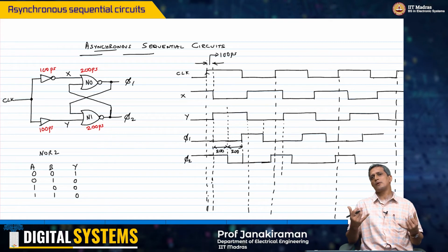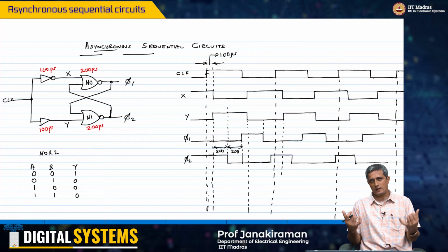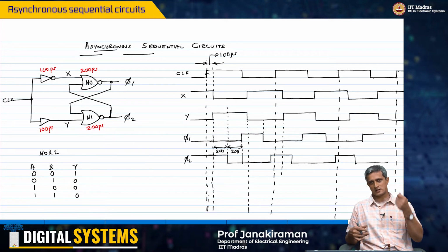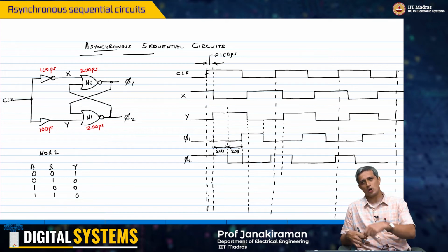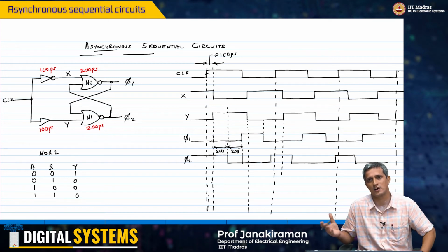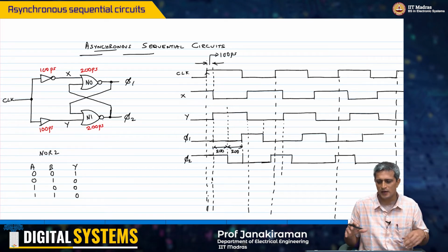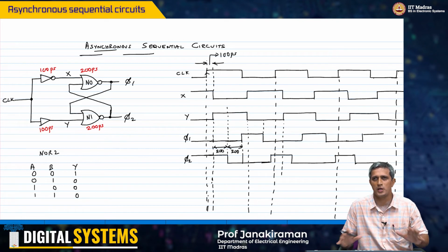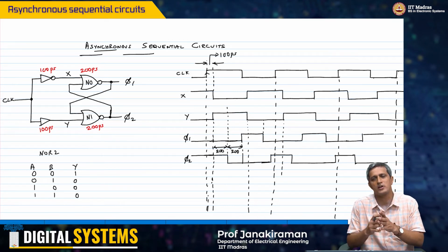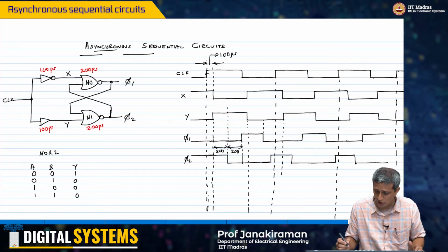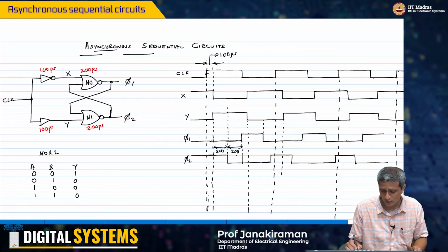You will land up with setup and hold violations if these clocks are different, right? And therefore you again capture these with asynchronous circuits and then pass them on to the next synchronous circuit as well, right? So with that, I'll wind up the discussion on the asynchronous sequential circuit design. And note here, we are now talking, by the way, of delay of 200 picoseconds and stuff like that.